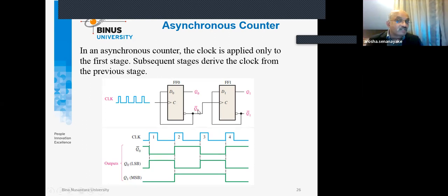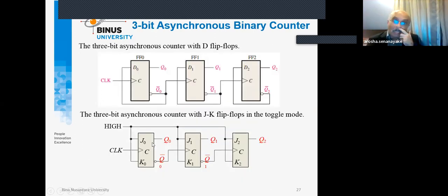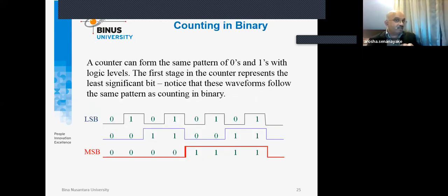So that is the clear difference. That means the clock pulse, as you can see, is double of this clock pulse, double T, 2T. Likewise, we can easily construct the counter like that, because what we understood here is that the least significant bit is exactly a clock pulse. The second bit is generated depending on double the clock pulse, and then the more significant bits follow.